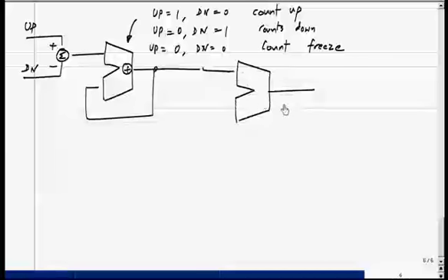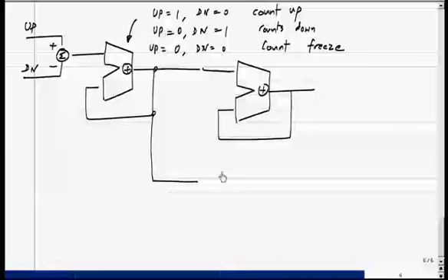So this can be implemented by a simple counter, and for the next stage we will need an accumulator. And this scaling is R1 C1 by Tref, and we want to implement everything digitally. So what we do is we take the integer nearest to this and use that for multiplication.